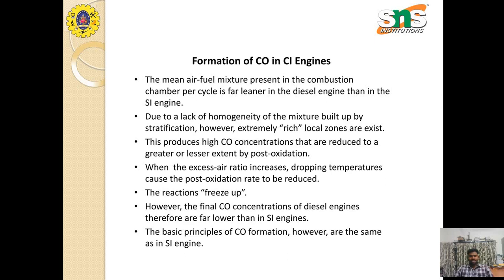The mean air-fuel mixture present in the combustion chamber is far leaner in the diesel engine than in the SI engine, the spark ignition engine. Due to lack of homogeneity of the mixture, rich local zones exist, which can cause incomplete combustion and lead to carbon monoxide emission.